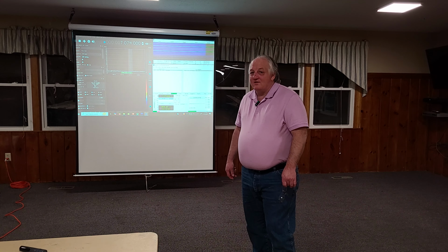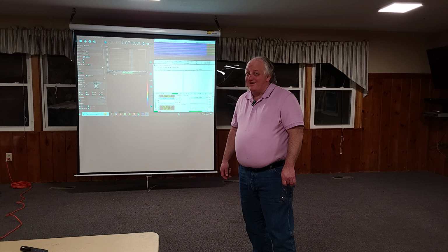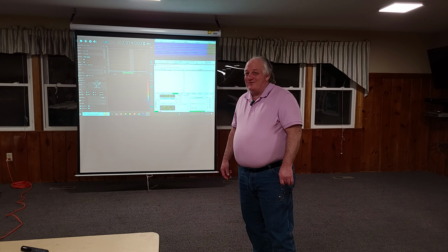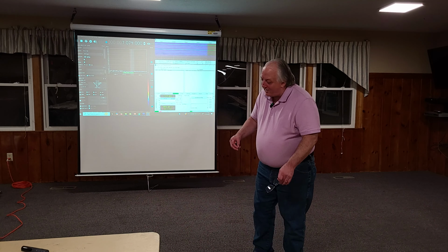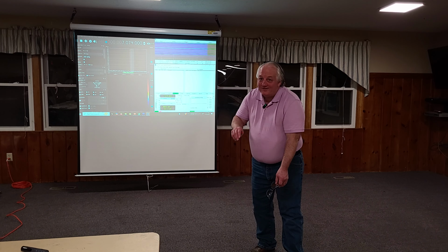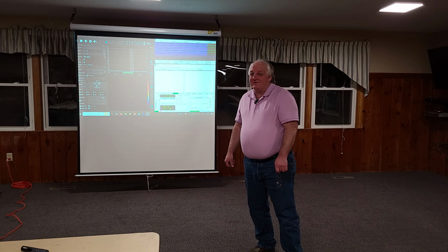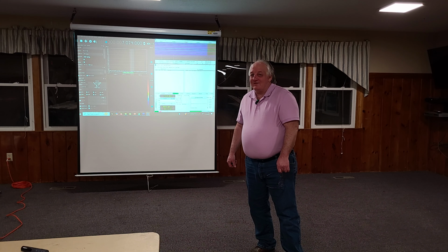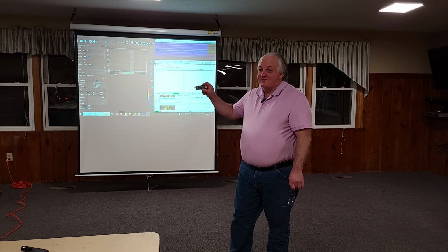So you were talking about 2200. That's a god-awfully long antenna. It is, and very few people that I know have an antenna that's full size. I use a 160 meter inverted L with a very large variometer, a very large coil that makes it look like a 2200 meter. So you have to play all the normal antenna games. Oh God, yeah. So this will work with this as well.